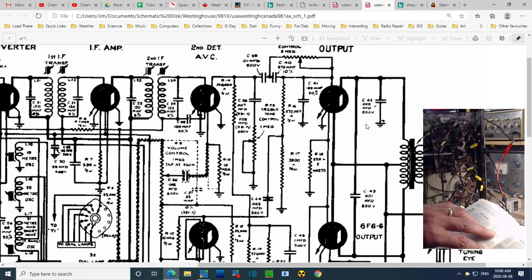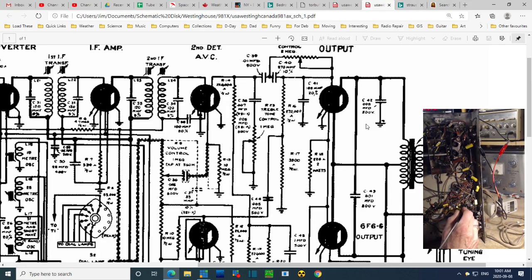So we're looking at a screen on 4, plate on 3. So we should be higher on 3 than 4. 4 should be tied together. And see the same voltage on 4. Okay, so this is 3. 3 is the low one. 3 is coming up, 175, and 4 is coming up higher. The plate voltage is depressed.